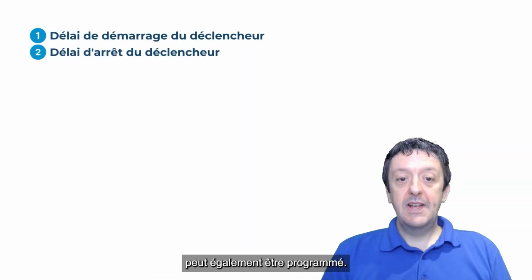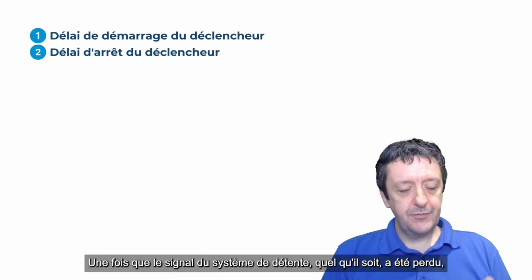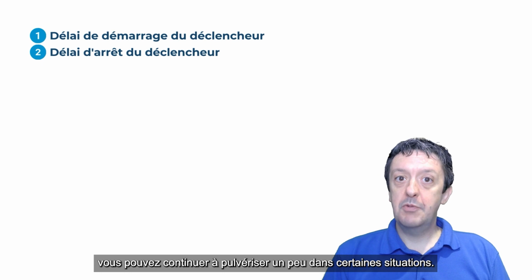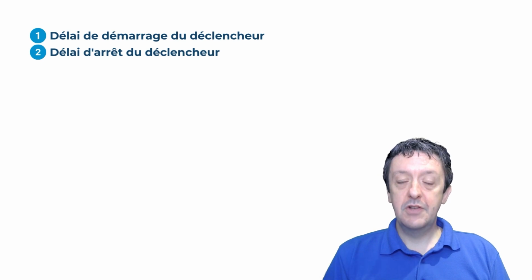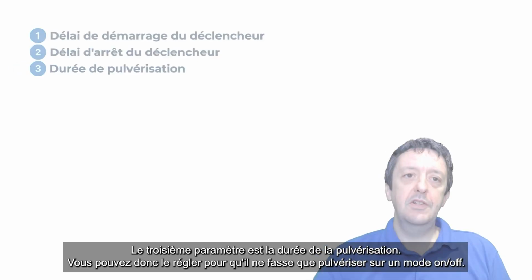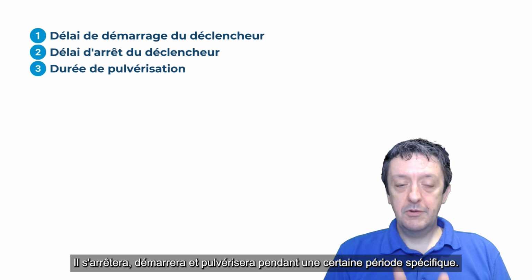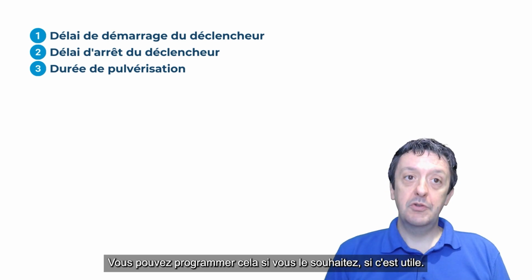A trigger stop delay can also be programmed in. Once the signal from the trigger system, whatever that is, has been lost, you may want to carry on spraying for a little bit in certain spray situations. You can program that in as well. The third parameter is spray duration. You can set it to spray on an on-off cycle, on a duration. It'll start and spray for a certain specific period, and you can program that in if that's useful.